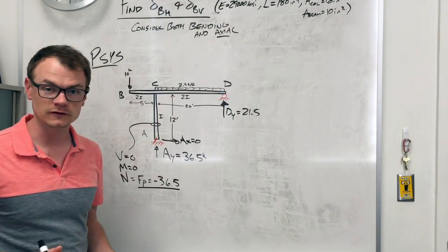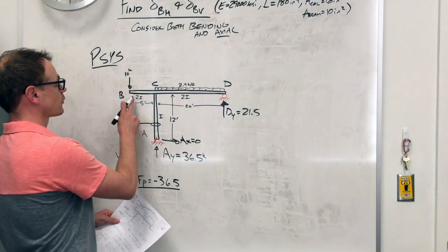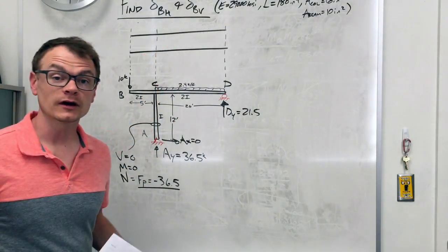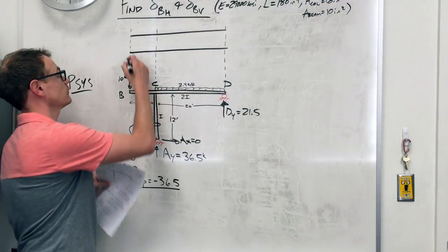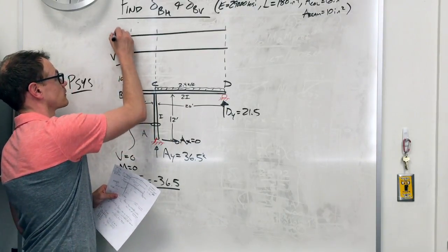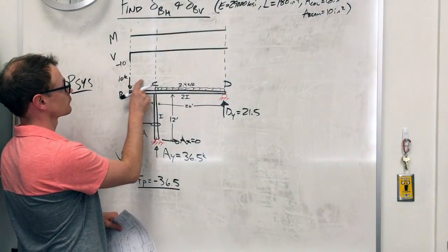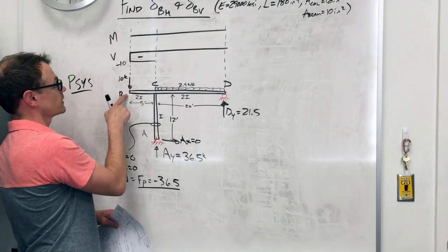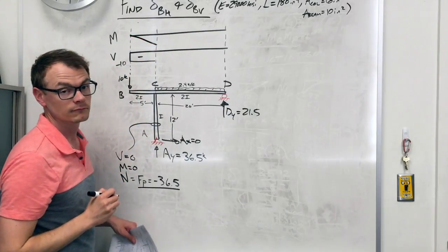Well, that column was pretty simple, right? Now let's move over to here. So I'm going to draw the bending moment diagram of BCD up above. Okay, so I cleaned this up. I have a 10 down, so it means I have negative 10 for shear. That was easy. Nothing happening here. There's no loading, so there's no slope. This is a free end. That means there's 0 moment. I have a negative slope. I go down. Negative moment.